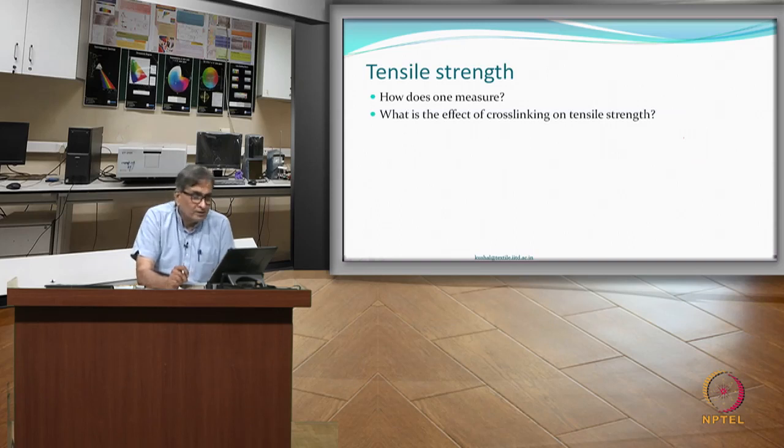What would be the effect of cross-linking on the tensile strength? So, we have done the cross-linking. When we have seen the crease recovery has improved, we are happy about it. The bending length has increased, we may not be so happy about it, depends, but normally an increase in stiffness may not be desirable after every finishing treatment. So, next is whether anything happens to the tensile strength.